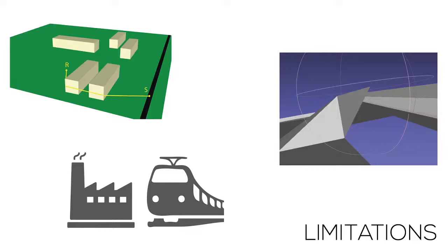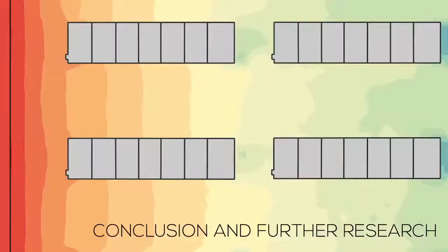Secondly, in the algorithm we created, direct and first-order reflections are taken care of. The noise software handles the propagation paths that are vertically diffracted. However, horizontally diffracted and multi-order reflected paths are not considered. At last, we currently only support roads as noise sources, but in reality there are many more noise sources, for example, railways, the industry, and airplanes, which are not considered but can definitely contribute to noise pollution.